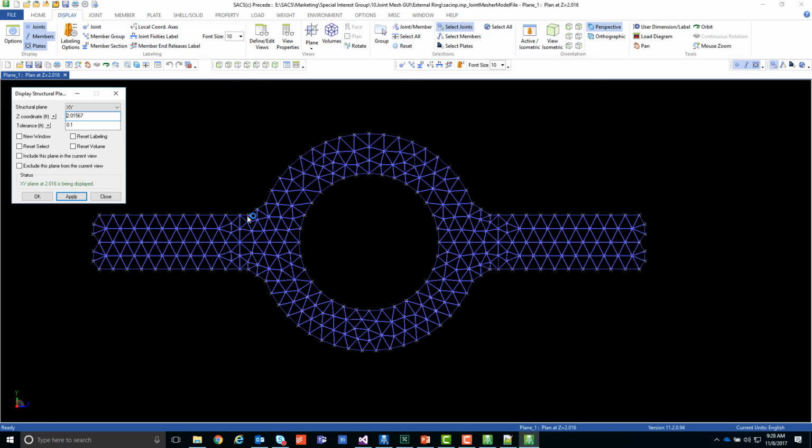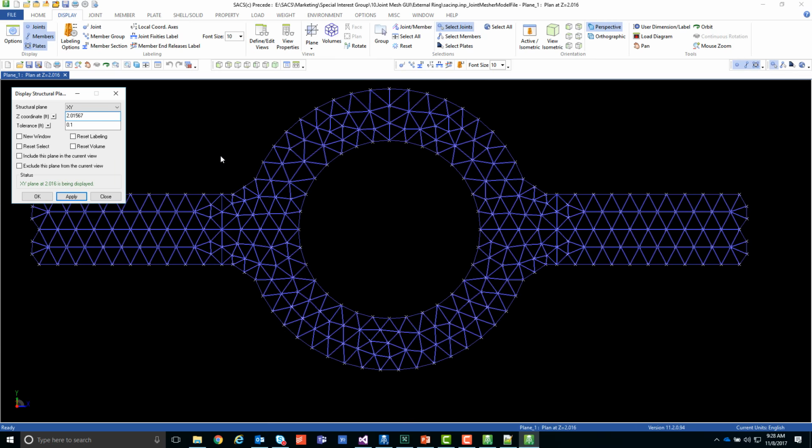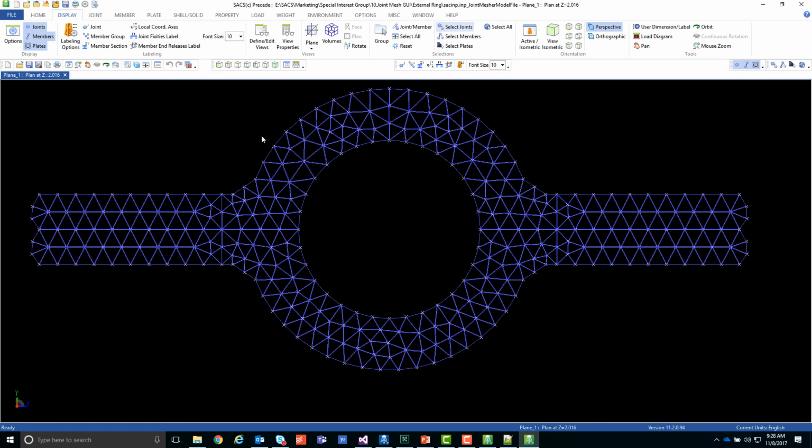We may want to increase the mesh intensity or decrease the element size too, because that arc transition looks a little flat there. Might want that to be a little bit smaller mesh size to get a better representation of that. But generally this is pretty good.